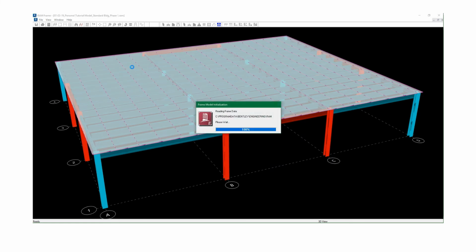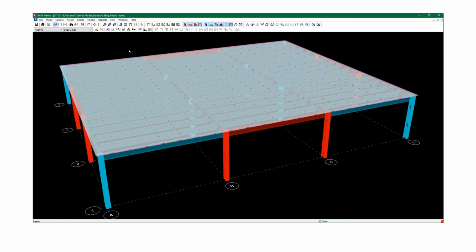Okay, picking up where we left off in the lateral frame analysis of the structure, we've seen that we had members that were reported as failing. We have to investigate why. Whenever that happens, it's actually time to ensure that all of your analysis is correct. I mean, you're always going to do that, but when that happens, for sure, you want to go back and check all of the previous settings and make sure that you aren't conservative in some instances, or that you've modeled everything correctly. And of course, you need to investigate in order to figure that out.